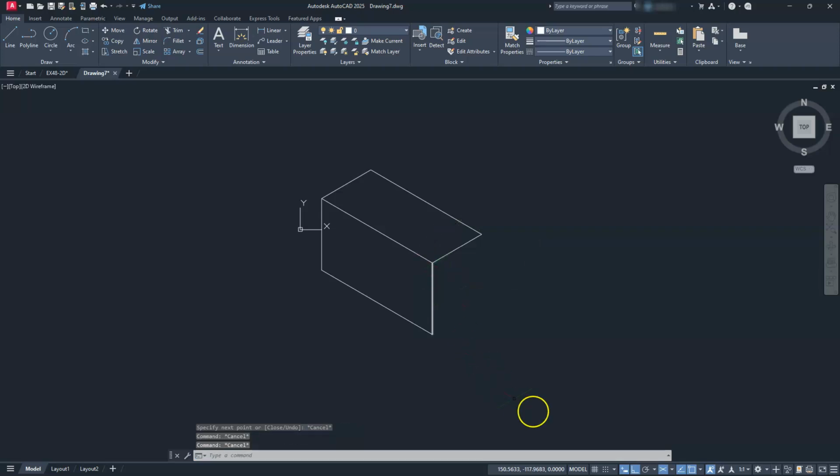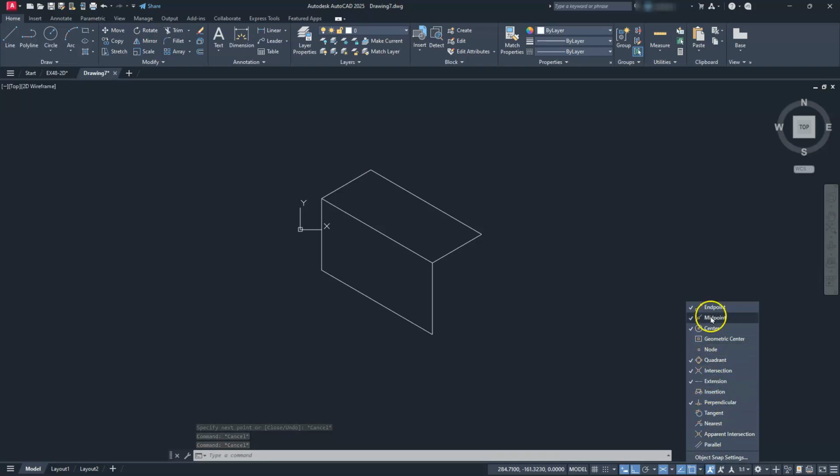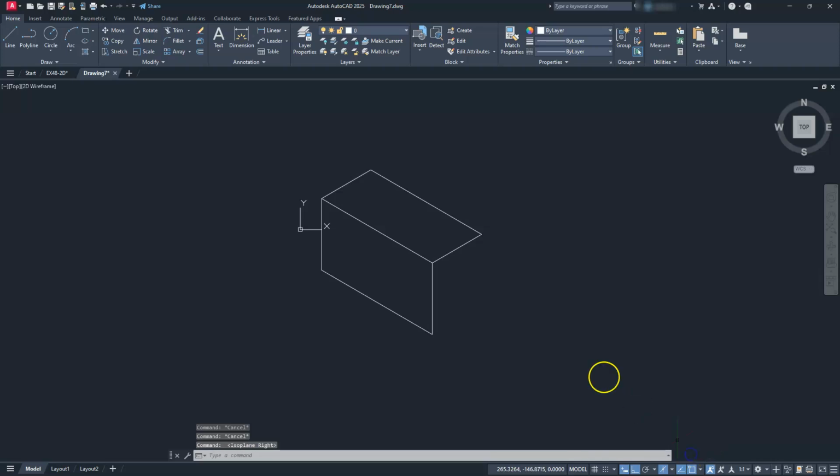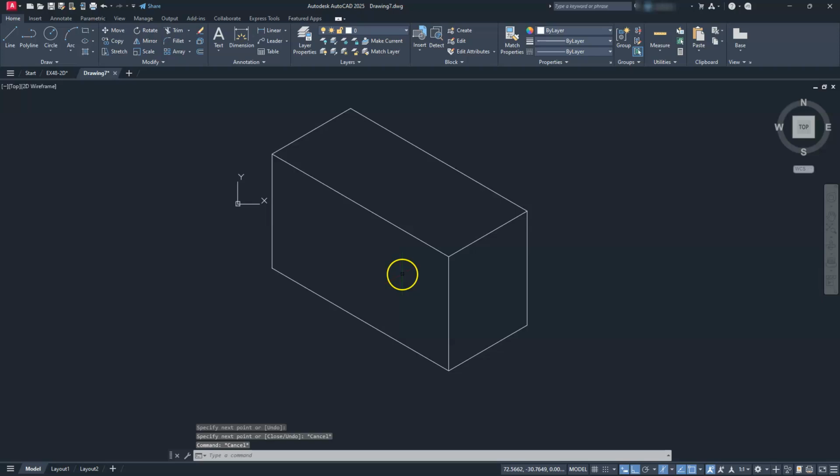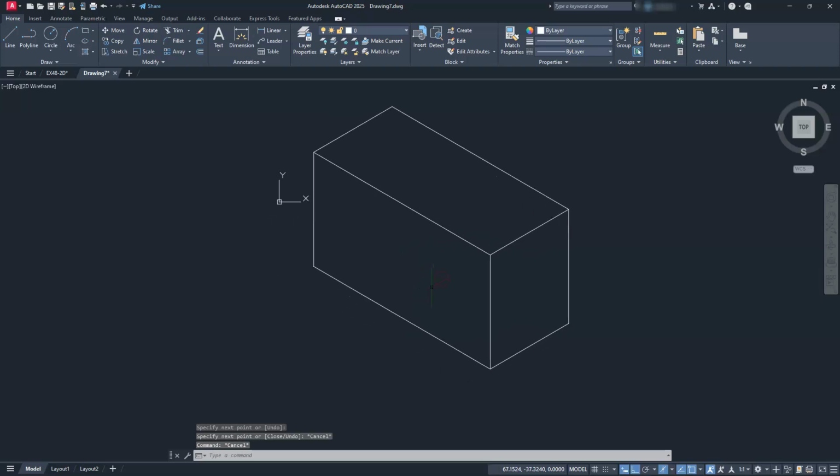Okay. Let's go ahead and switch to isometric right. Click the wrong fly up. There we go. Let's do a line again. So I'll just go to L, enter. And then I'll click at this endpoint here. I'll go this direction, a distance of 40, and then we'll just go right up to that endpoint. Okay, so this is the basic shape that we have to create.